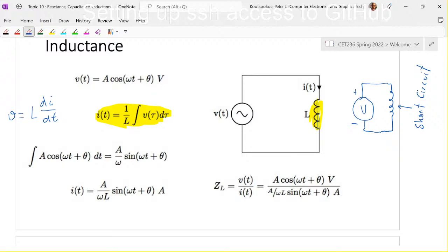If you've got current flowing and all of a sudden you open the switch, that makes di dt go very big very quickly, which makes v go very big very quickly. In order to make that spark on your car's engine, you need that high voltage to bridge the gap between one side of the spark plug and the other side, in the center. Right? So that's pretty important.